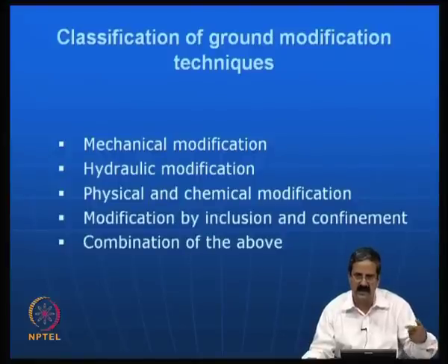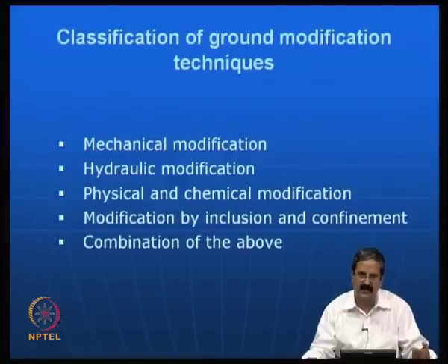We have introduced some sort of reinforcement in the soil, and if you apply load, the load gets transferred to the reinforcement and soil, and then there is friction between the soil and reinforcement. Because of this friction, that particular component will help in taking the extra additional load. The other important point is the confinement effect.